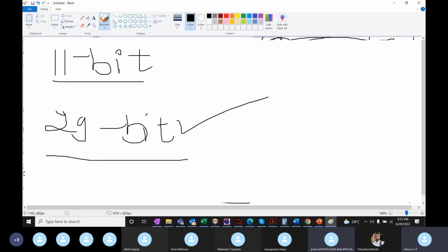Just now we have seen it, and you guys know the answer also. I just want you to think and answer. If we are sending more than 11 bits of data, we need to take 29-bit, right? No, you are not sending data. That is an identifier. You are sending the data with that identifier to identify the input, whether it is the front camera or back camera or whatever it is. It's an identifier. It's not the data. Correct, right?